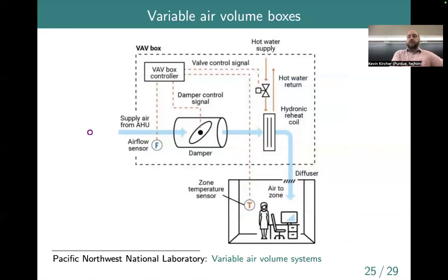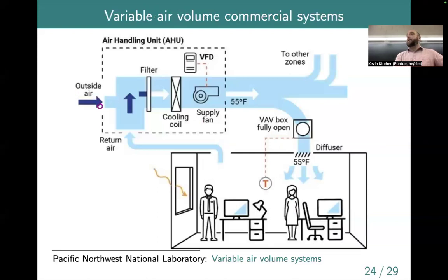So it gets the cold, dry supply air from the air handler. And then again, there's a motorized damper here with a controller on it, which is getting a measurement of the indoor temperature, and also other things typically, like maybe the CO2 level inside of a room. We talked about that with this room specifically, how if we have a bunch of people exhaling repeatedly, CO2 levels can build up and that can lead to feelings of fatigue and stuff like that. So that's one of the reasons that in the air handler, we mix in outdoor air: basically to dilute the concentration of CO2 that's coming back from the return air.